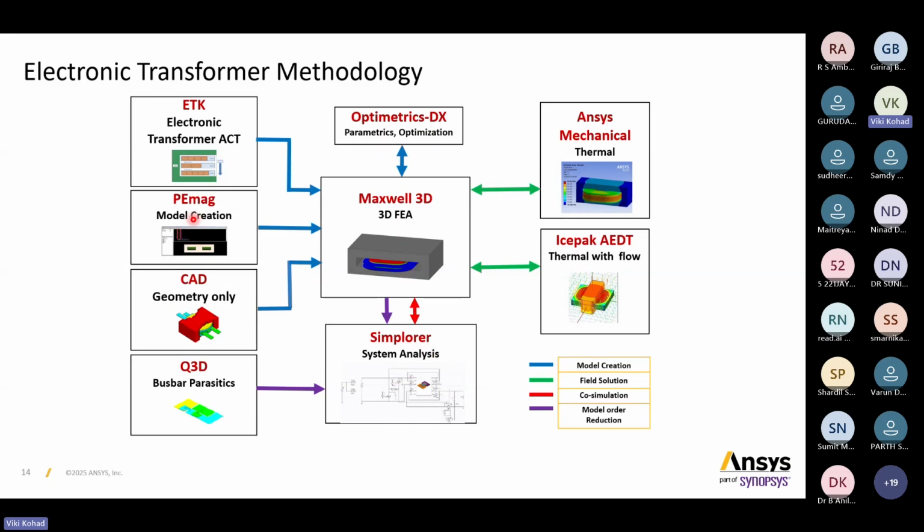Now, PMAG is the more basic tool for transformer design. Any type of transformer you can design by using PMAG, but since PMAG is a more basic tool, you have to put in more manual effort than with the ACT extension to use PMAG for the transformer design.